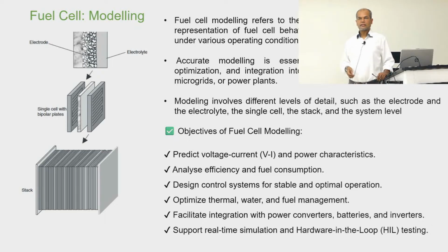So, let us say for example you have a 5 kilowatt electrolyzer in a lab or in your building, and you want to know what sort of fuel you need for a particular period of time or to supply load for a particular application. That is why you need the modeling. And if you want to design control, the first thing, as you know, is that we need the modeling. If you want to optimize the thermal, water and fuel management, you also need the modeling.